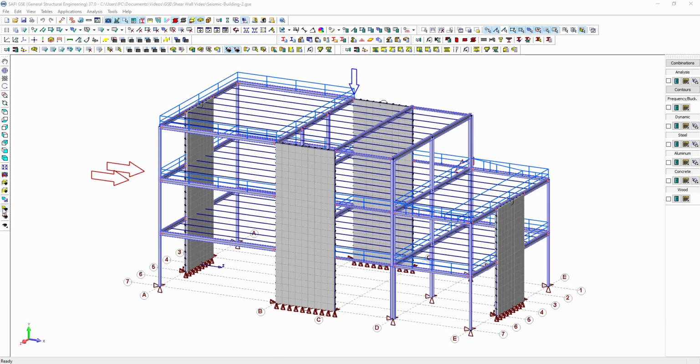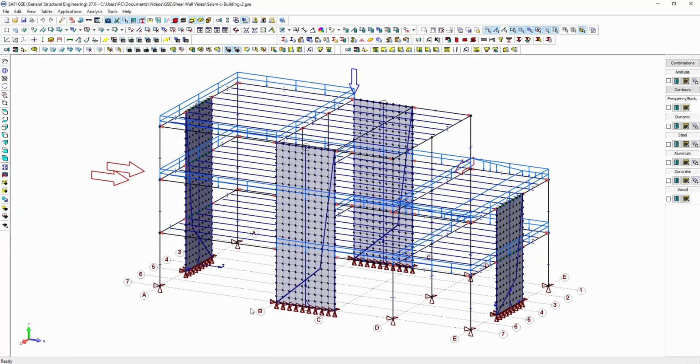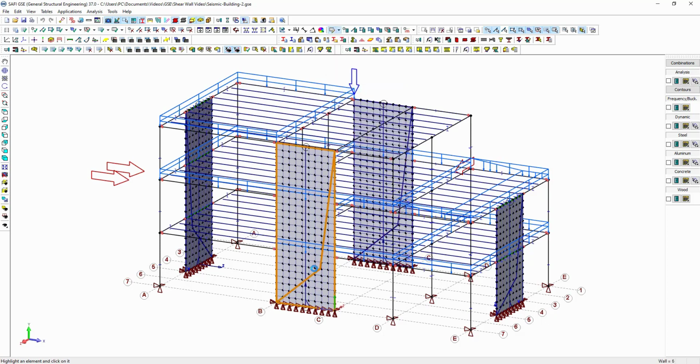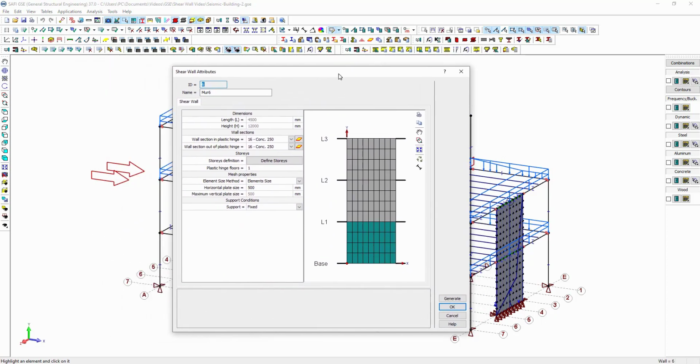The first new thing in the update 37 is that the shear wall can now be edited. As you can see on these 4 concrete shear walls, there will be this diagonal line that goes across the face of the wall. This is to signify that we use the Add Concrete Shear Wall button. This is the new feature from this update, where you can choose to add these types of elements. Once they are put in place, you can go in the Addition tool menu of this wall and we have this window. From here, we can see the overall shape of the wall.